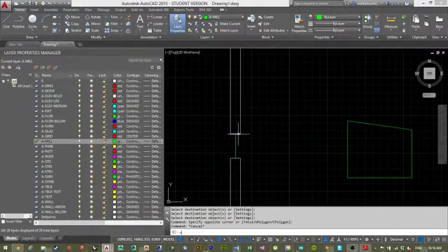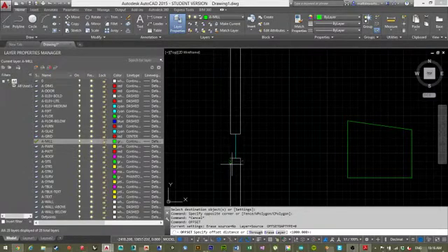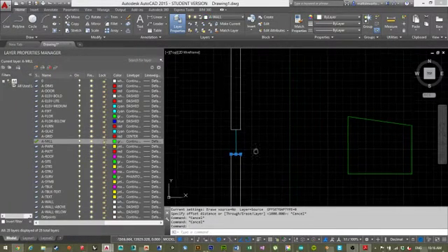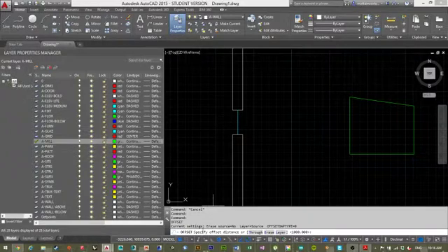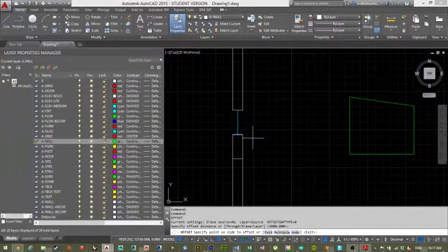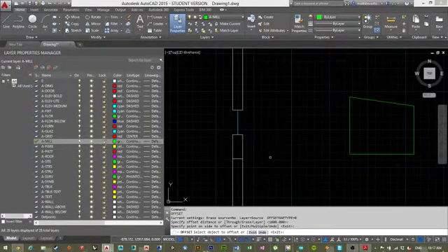So when I go offset, it'll ask me, select that, offset. It's going to ask for how long, and the last dimension is always in there, so I'm just going to keep it 1,000. Press enter again, and if I have it below, it shows the line here. If I have it above, it's right there. Wherever you put your cursor, that's where it's going to go.